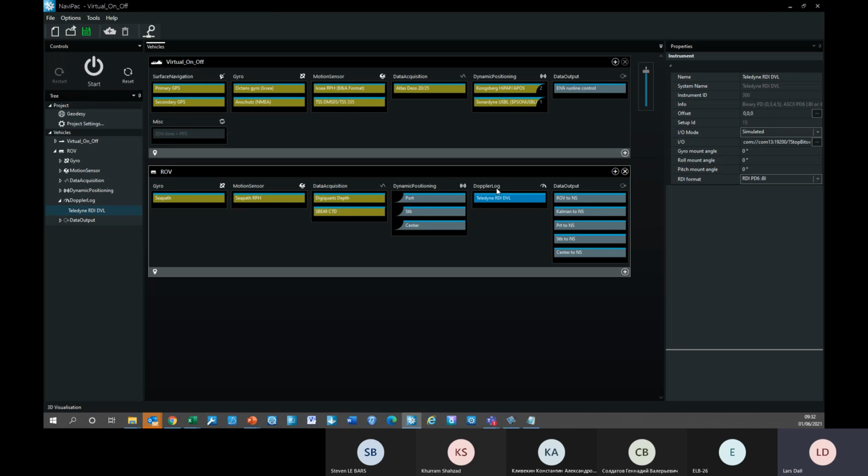The Doppler log has a very high relative accuracy, a lot better than the USBL system. But it doesn't know where in the world it is. It just knows that I'm moving with this speed, and now I'm moving that speed and in that direction, etc. But the point is that if you're combining your USBL system, which is noisy, well, basically it's noisy, but it knows where it is.